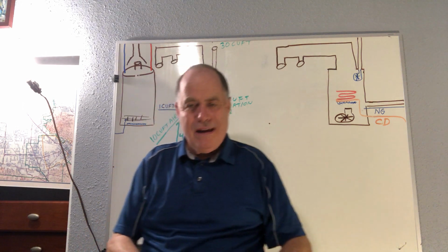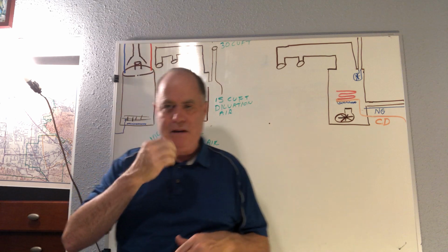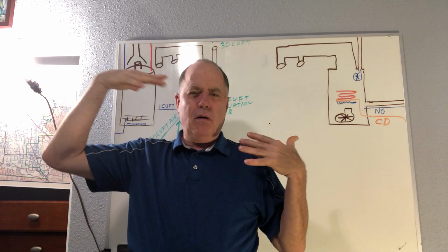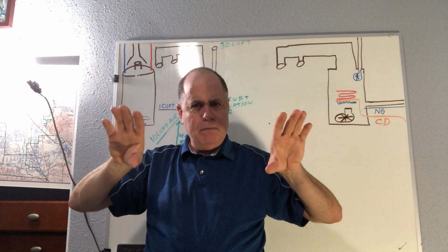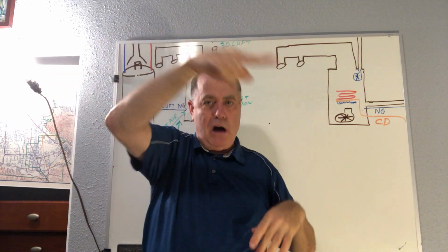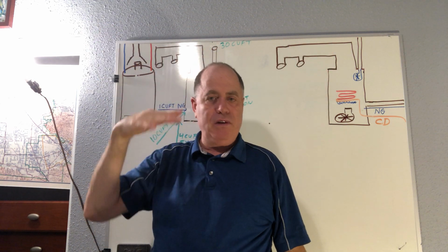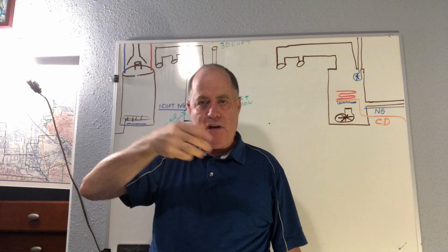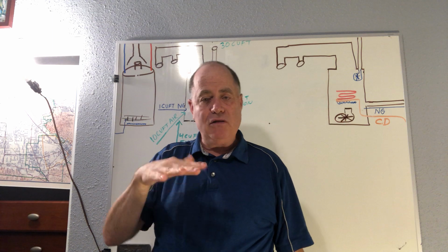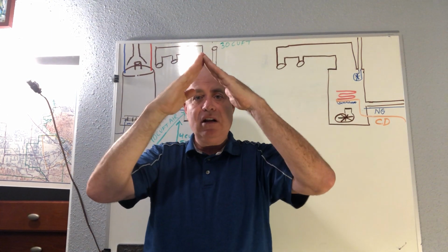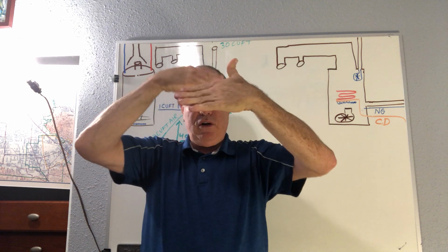Okay, and also this idea of the one or two openings, let me give you that concept a little bit. A lot of times you'll find vents all over the place at the bottom of the attic with screens on them. If you walk around the outside of a house, you'll see that. Those should not be blocked with insulation. Sometimes companies come and do blown-in insulation and block those. That shouldn't be. They should rake that out and tamp that down. And then at the top of the house, you'll have the gable vents off of your triangle at the end where you have these louvers.